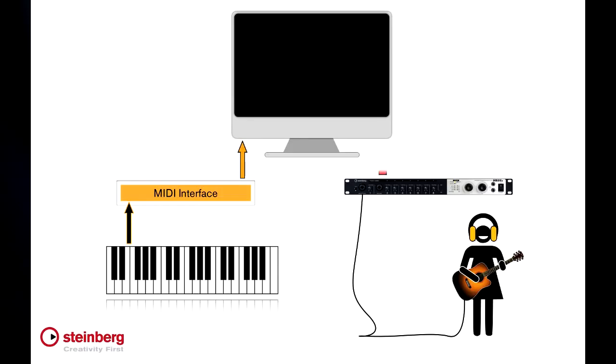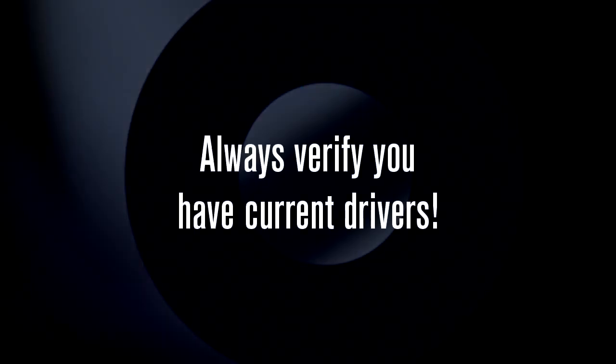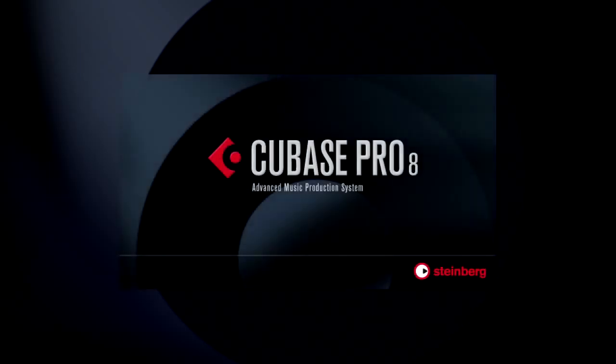Now follow the manufacturer's instructions to connect the amps, speaker, headphones, and other equipment. Connect the interface to the computer by USB or FireWire as appropriate. Turn on the interface, and then the computer. And make sure you have the latest drivers for your interface. Even if your interface came with a CD of drivers, you should check the website for any updates and download them if needed.